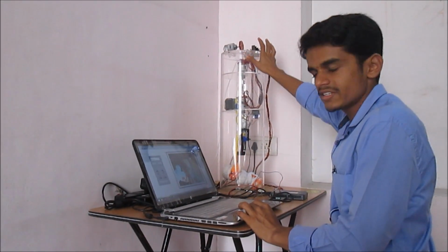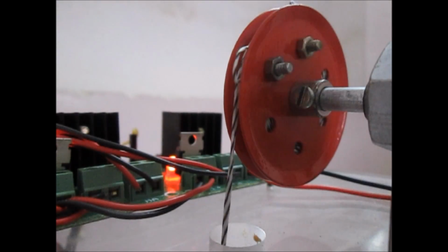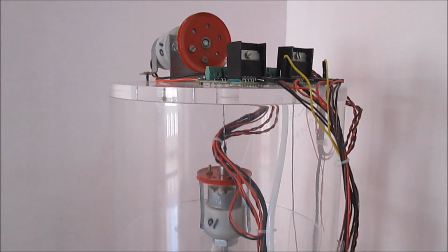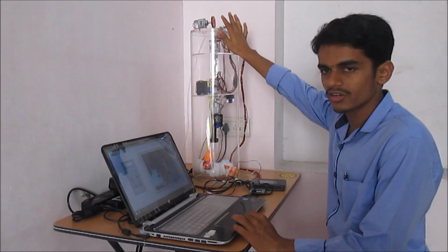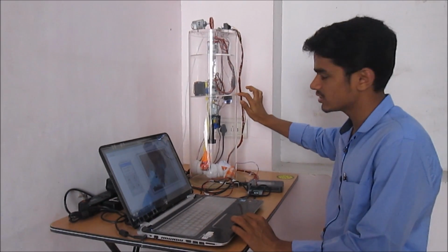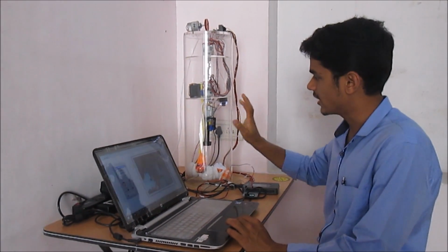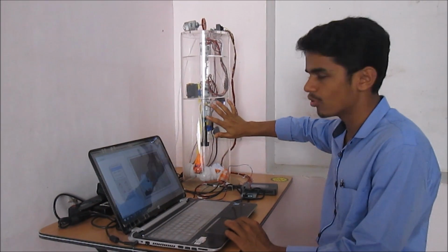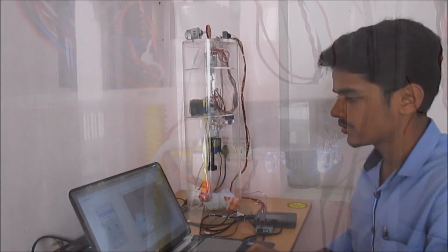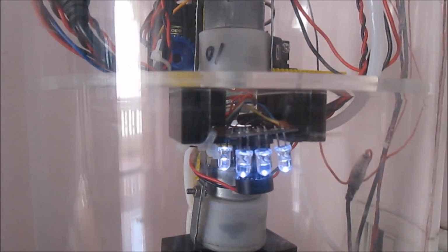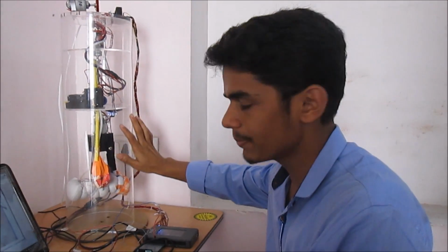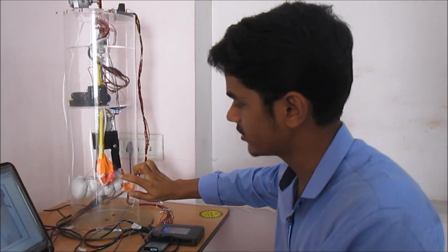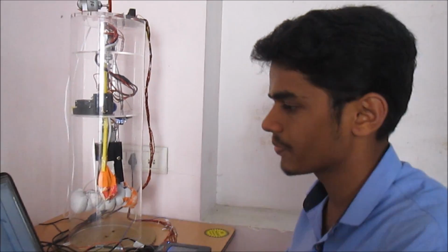The pulley system descends the robot inside the borewell. Once the child is found, the pulley motor is stopped, and now, using the rotation of the base disc having the camera, a gap between the child and the wall of the borewell is traced. Once the gap is traced, the stick having the balloon at the end is inserted below the child.